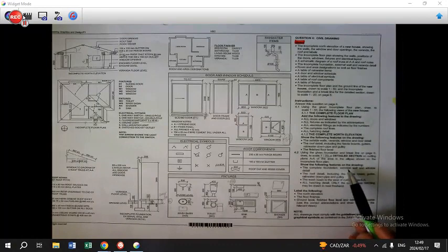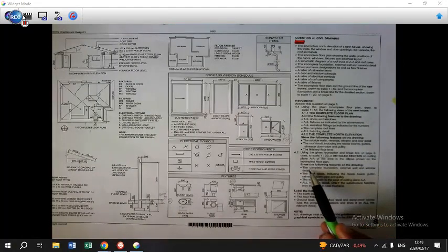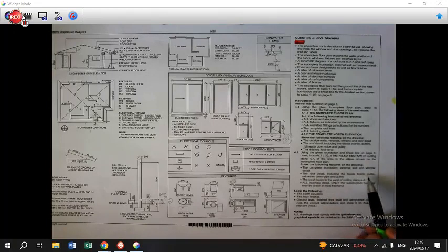You need to show the following features on the drawing. Bulleted point 1, the complete foundation, external wall and window detail, the roof detail including the fascia board, gutters, rainwater downpipe and gully, the wash basin to the west of cutting plane AA, all the hatching detail, and keep in mind the substructure hatching may be drawn neat freehand, but of course we are going to apply it with our set squares and T-square. Learners, please label the following on the section: the north elevation, your floor finish, your ground